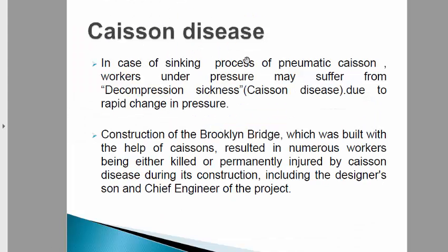And the main problem is caisson disease. In the sinking process with a pneumatic caisson, workers under pressure may suffer from decompression sickness. This caisson disease is due to rapid change in pressure, because in the pneumatic caisson we lock the air chamber and do not let air pass out of that chamber. We do this so that the sinking of the well is done properly, that's why we provide the locking of the air. But due to that, caisson disease occurs.